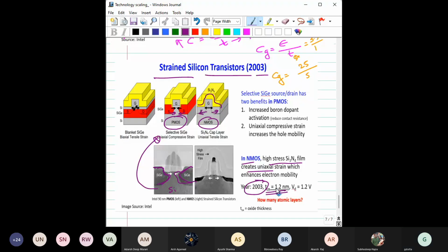It is basically a molecule. So by that silicon dioxide structure, and it is only 1.2 nanometers, means 12 angstrom, right? That's why there was no choice but to introduce the high K, because otherwise the leakage current, even in 2003, even in this technology node, leakage currents were pretty high.